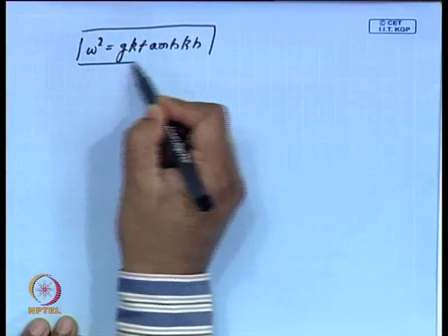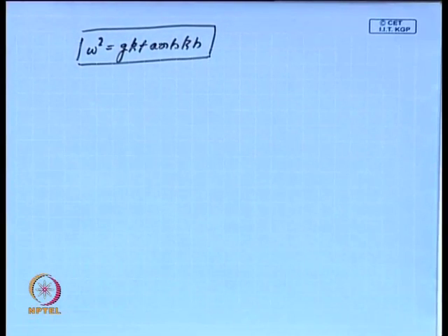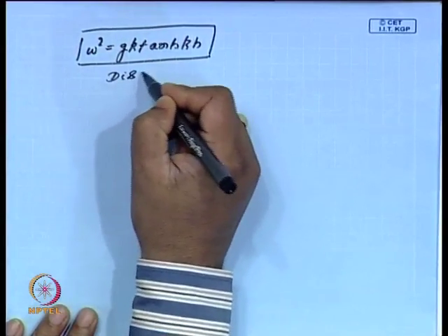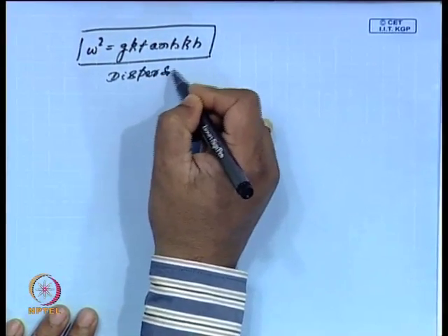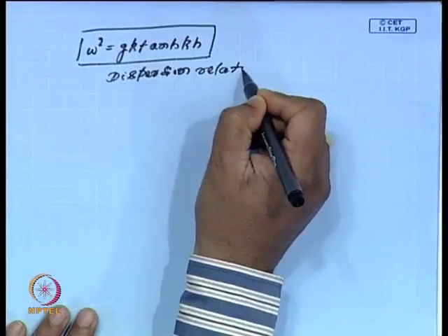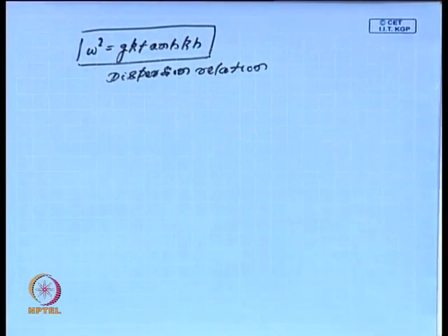Just substitute phi in the surface condition phi_tt plus g phi_y equals 0, and that gives us this dispersion relation, which I was talking about in my last class, in my introduction to water waves. So, this is the way the dispersion relation has come, just by substituting the form of phi in the free surface boundary condition.